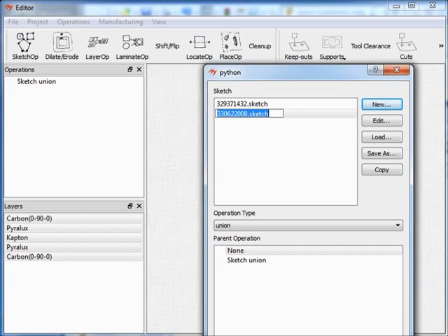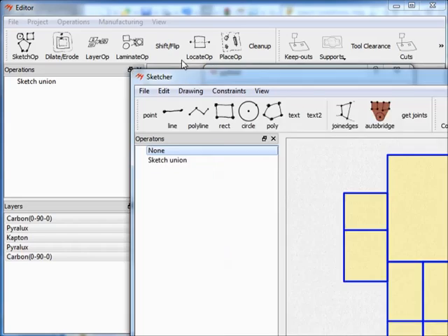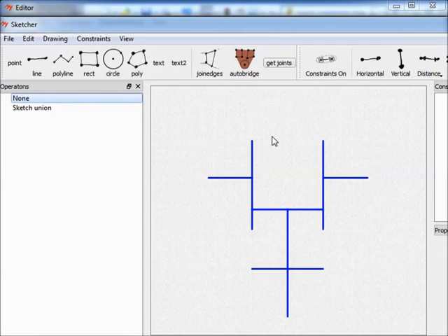So we need to separate them, and we also need to define where the joints are. By copying that original sketch, you use this function called getJoints, and that will find all the common edges and allow you to use the lines that are generated to create joint descriptions or to separate faces that are touching and merged. So what I'm doing right now is deleting all of the lines that were generated automatically that aren't going to be joints.